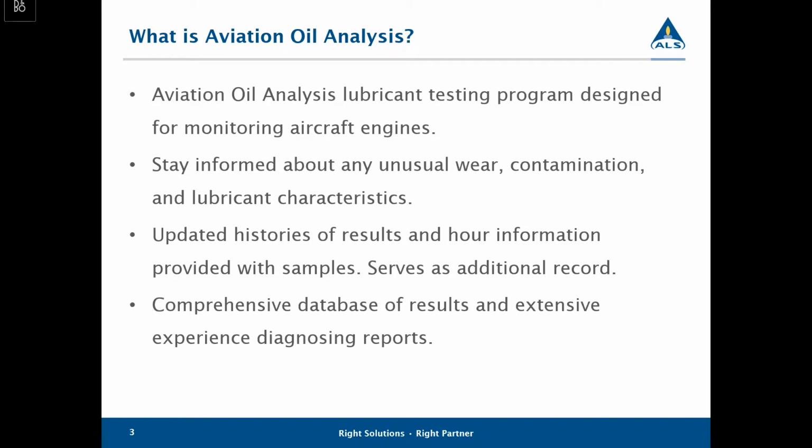Along with aviation oil analysis, we have a very comprehensive database of results and extensive experience in diagnosing those reports and results. As I said, within a few years' time, I was able to review close to 50,000 reports myself, and we have a wide range of diagnosticians that work at ALS. And as we work across different industries, we gain knowledge from each, and with practice, you gain that knowledge to be able to evaluate very effectively whether or not those results are good, if something's abnormal, maybe even how to be proactive about them.